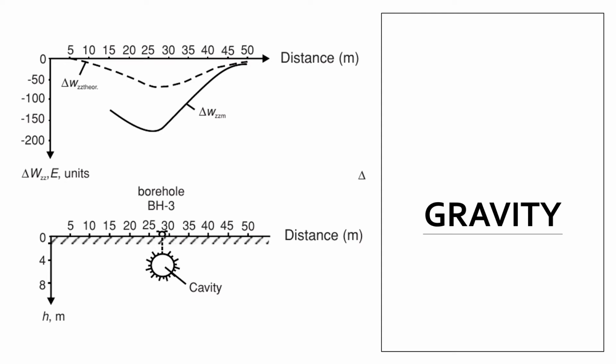So water or air has a low density, and when you're doing a gravity survey, you can expect a cave to register a low gravity reading here. So in here, we are registering a highly negative gravity reading. This doesn't mean that your object has a negative gravity. It only means that you have a relatively low gravity reading here. Okay.